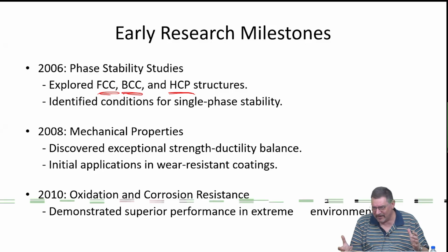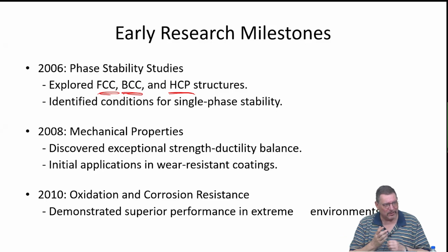This is again because mostly we're talking about metallic systems with rather equal properties of the constituents, and these systems tend to make densely packed structures: FCC, BCC, HCP. The more open structures are left for more covalent systems, or at least stronger covalent contributions to the binding energies.